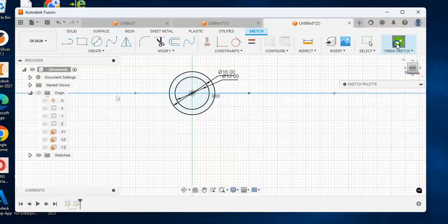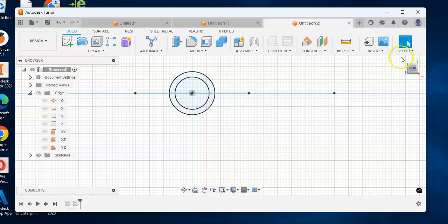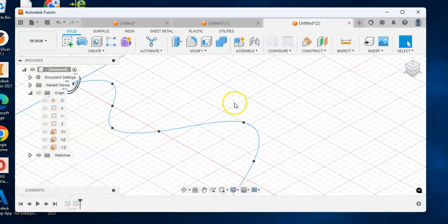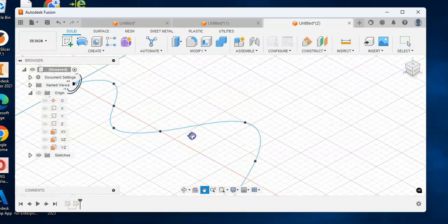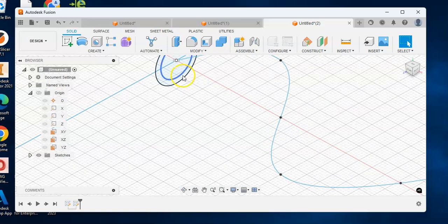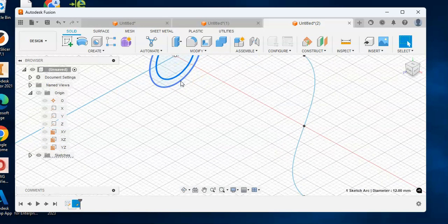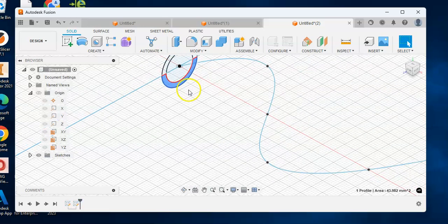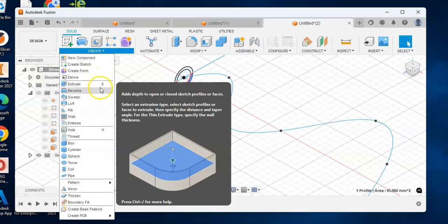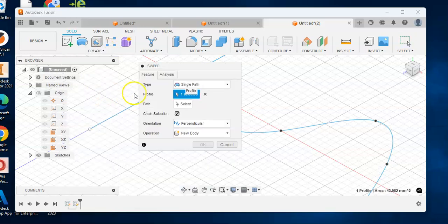so now we can finish our sketch, and now what we see is that we are somewhat set up to run our trough along our zigzag curving path. So we'll come in, we'll arrow in, try and select the bottom part of the profile, pull down, create, sweep.